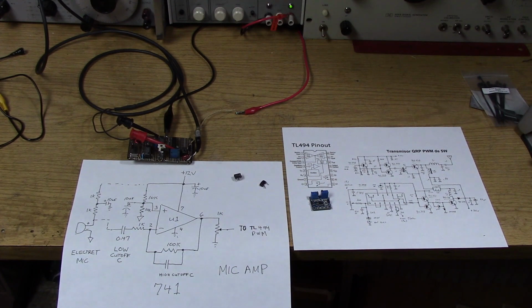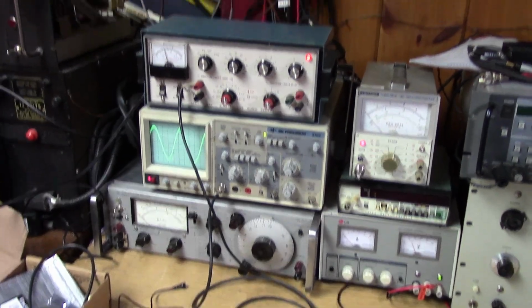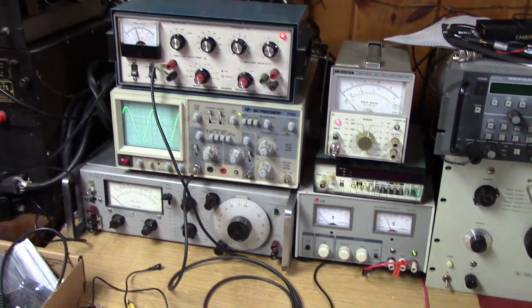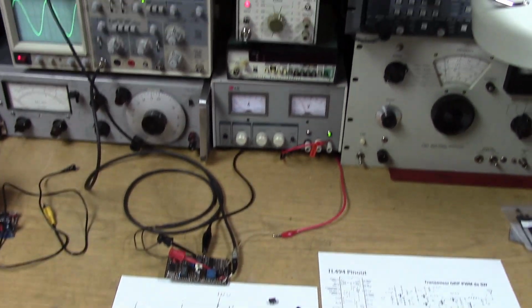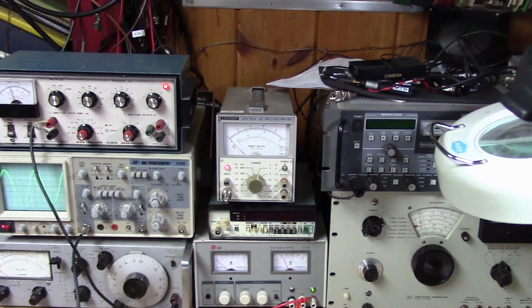Also, when you're using a test signal, you want to have a good solid output, but you don't want to be in clipping with the amplifier. So I figured about 10 millivolts RMS on the input was a good place to start. And with 10 millivolts RMS, we should be able to get something like 1 volt RMS out. So let's take a look at the scope and see if we have a nice sine wave. We do. So we're not overdriving the amplifier. And let's look at the RMS voltmeter.